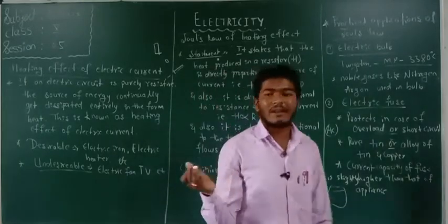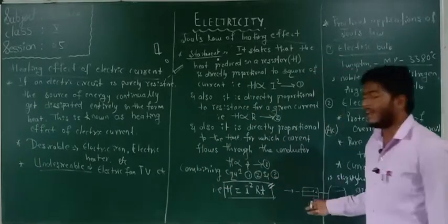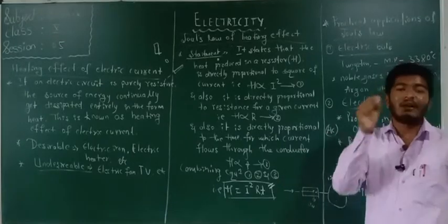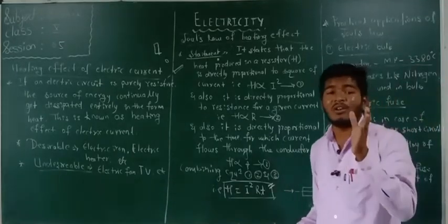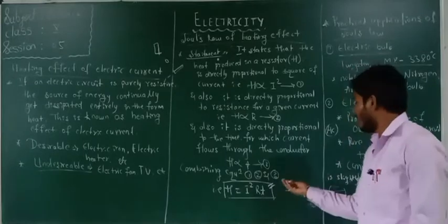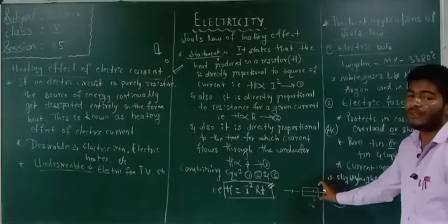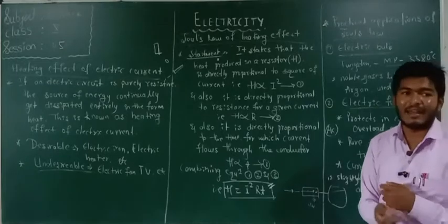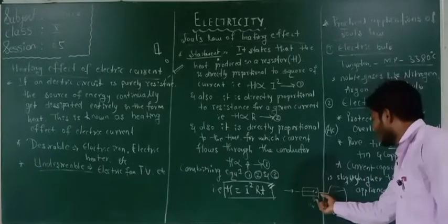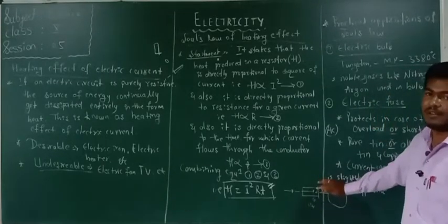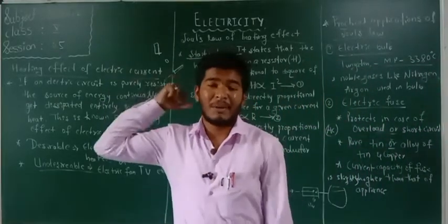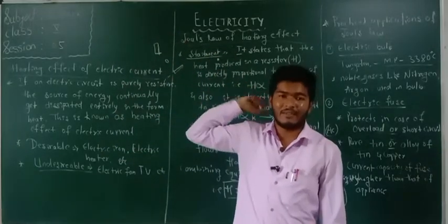When a large amount of electric current heads to our electrical appliances, it first enters our fuse, which has a small thin wire made up of tin, or of tin and copper. It has a low melting point. When more electric current enters the fuse, the wire gets heated and cut, and the continuity of the circuit is broken, so our electric appliances will be safe. Have you understood? This is the mechanism we use based on Joule's law, or the heating effect of electric current.